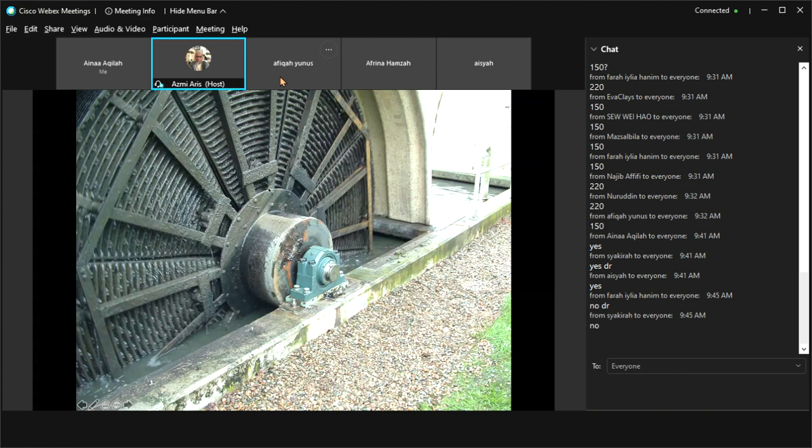So these are some of the main issues related to this rotating biological contactor, making it not favorable in the market, especially in Malaysia, although some other parts of the world are still using it, because of the broken shaft and also because of the corrosion at the metal ball bearing caused by the exposure to the water. That is some introduction on rotating biological contactor.